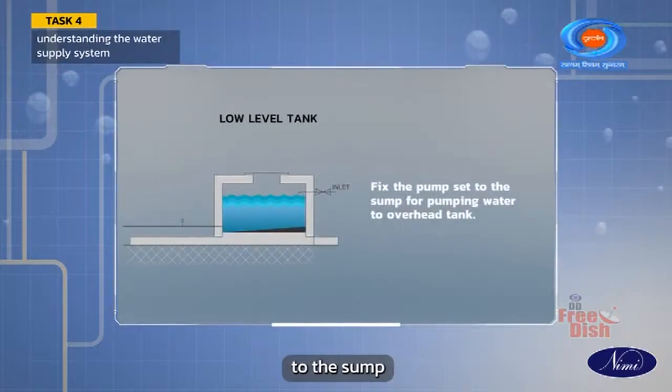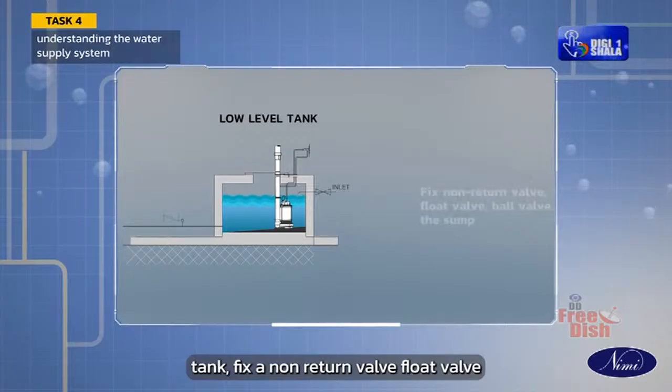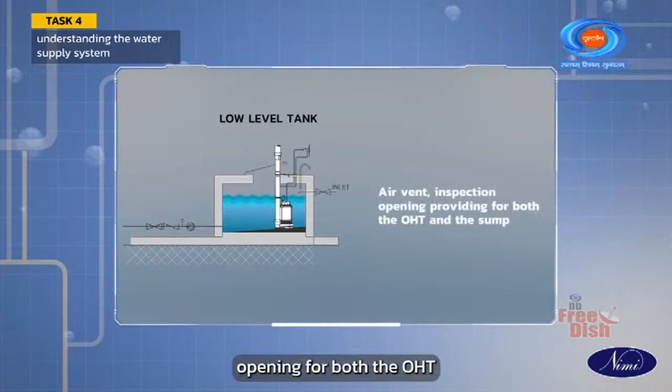Fix the pump set to the sump for pumping water to the overhead tank. Fix a non-return valve, float valve and a ball valve to the sump. Provide an air vent and an inspection opening for both the OHT and the sump.